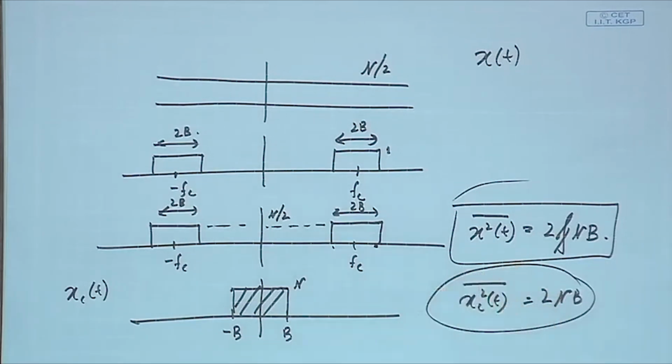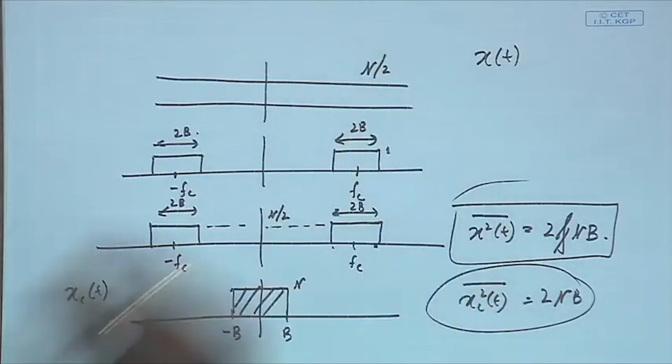Okay. So, in our noise analysis we will be taking the noise as this, which is a flat spectrum, and whichever filter we will be employing, be it low pass or band pass, we will always take them to be ideal, because if you do not take ideal then probably the analysis will become too complicated. You can always do that, but if I wish to compare the performance of two systems, I will take an ideal filter for both of them and then analyze it, because life becomes much simpler. Okay. So, that is something we will be trying to do.